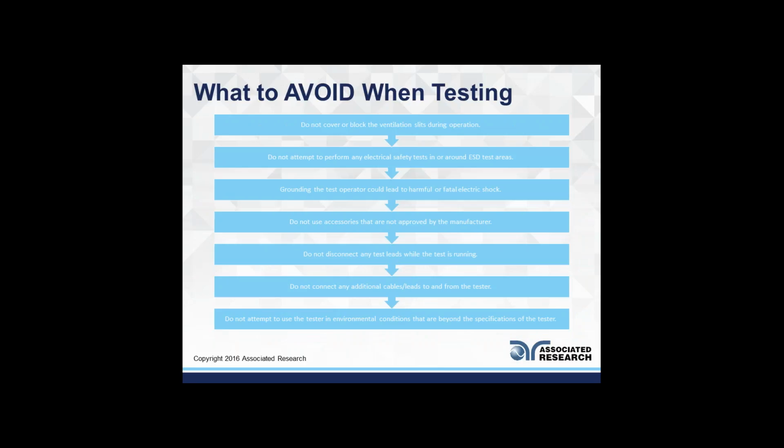You want to make sure we recommend a yearly calibration, since these are measuring instruments. They could be off, and even the output could be off. So if you're applying 1,000 volts, and it's not calibrated in 5 years, you don't know if that 1,000 volts is 1,500 or 900 or 800. So in that case, you want to get things calibrated with the recommended calibration cycle by the manufacturer.